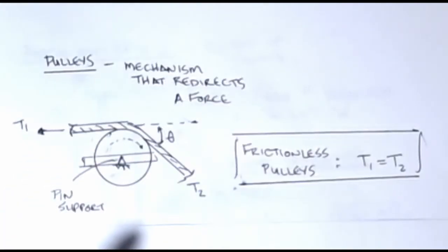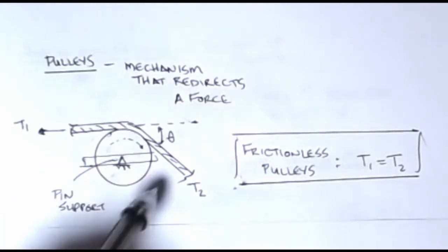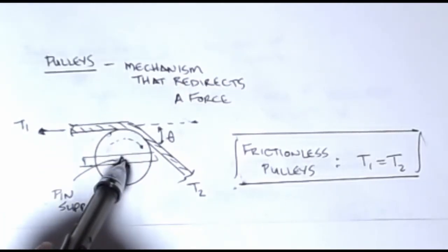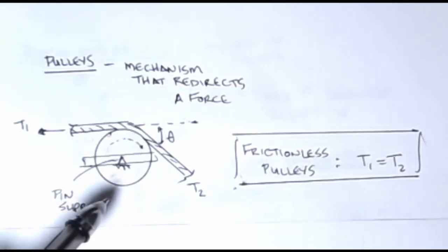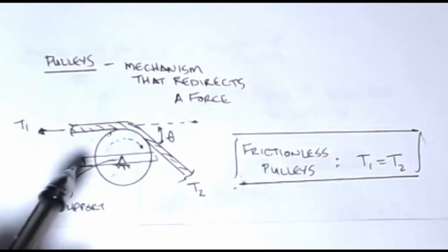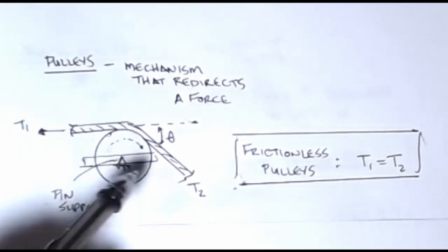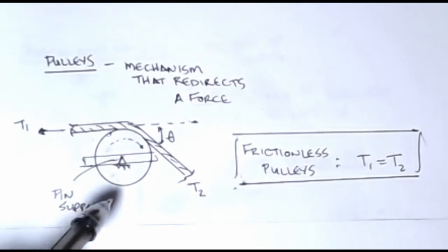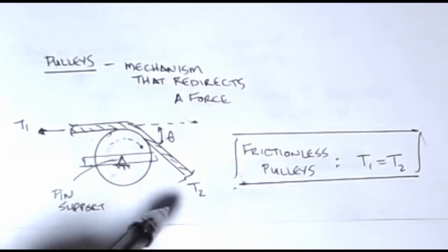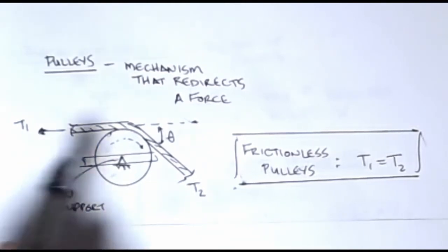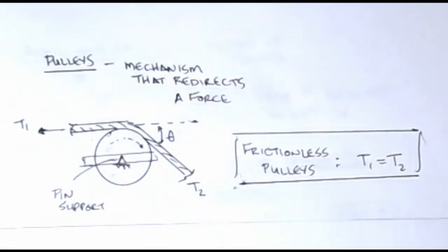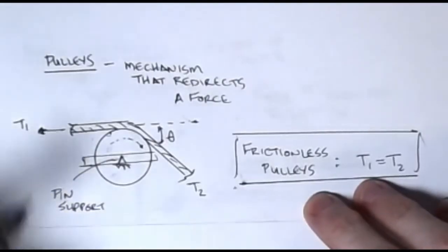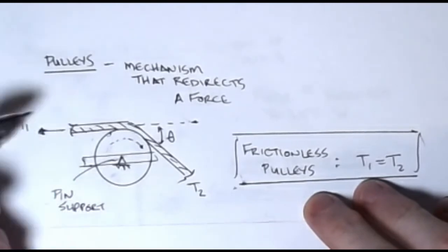Now, in most statics classes and really in most engineering problems, we assume pulleys to be frictionless. There's some friction that would occur at a number of locations. We could get friction in the bearings, friction of the cable as it moves past the pulley, all sorts of places. So just to get our heads wrapped around the mechanics and the basic statics equations, we're going to neglect friction for all cases here. When we get to our friction topics later in the series, we'll reintroduce pulleys and wrap angles, in which T1 doesn't equal T2, but for now T1 is assumed to be equal to T2.